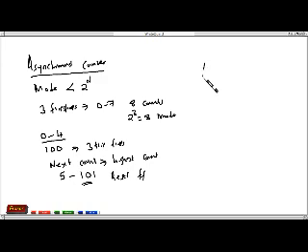In our case, we have used the JK flip-flops, and in our JK flip-flops, those are the inputs, those are the outputs, and the inverted outputs. The flip-flop has a reset pin and a set pin, and both the set and reset are active low.